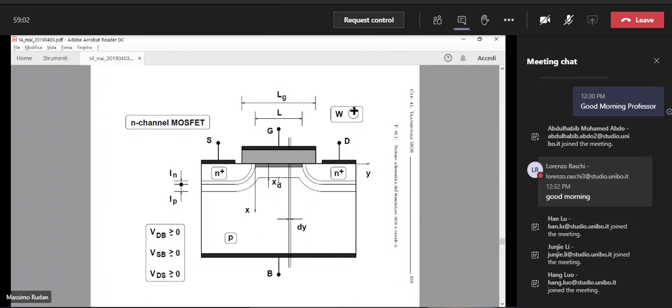You remember, there is a depleted region in which the main contribution to the charge density is due to the dopants, and then we have the surface in which we have the electron layer. So the depleted region has a width, and we cannot call it Lp because the symbol Lp has been already used in the junction. So from now on, when necessary, the extension of the depleted region under the gate will be called XD instead of being called Lp as we did before.